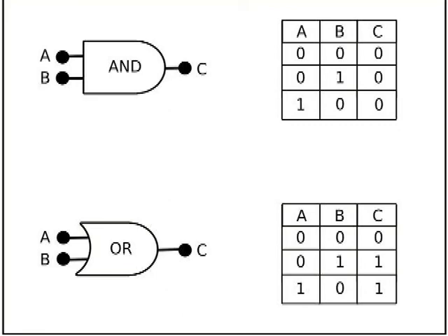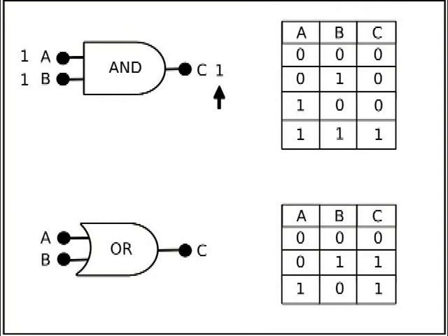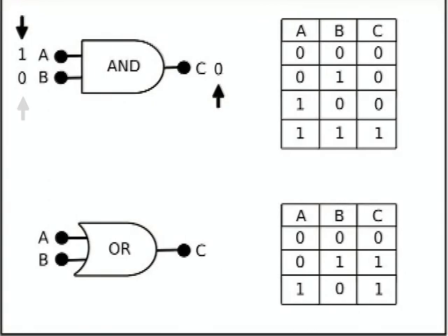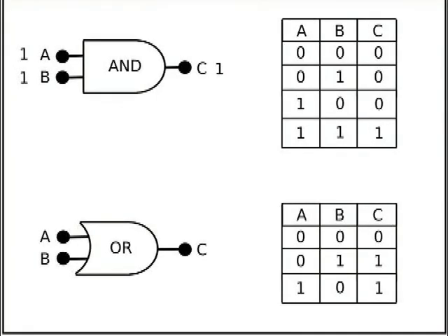An AND gate will produce an output of 1 when both inputs are receiving a 1. That is, the output of a 1 requires that the input A and the input B each receive a condition of 1 each. If only one input receives a number 1, the output at C will be 0. The truth table illustrates this behavior.